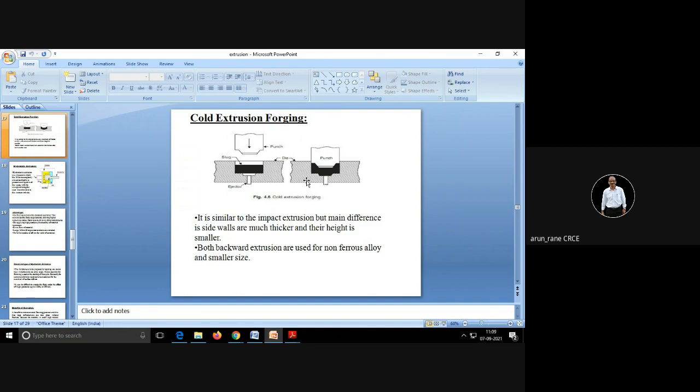The people who are into die design, if they look at the component, can easily identify where the injection point is, that is the gate, and where the ejection point is, from where the component is ejected and how the component is injected. Because looking at the parting line, the gate mark and the ejector rod mark, an experienced person can very well understand.